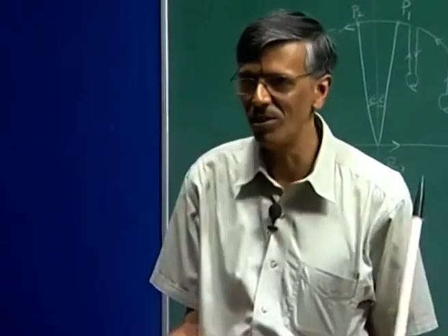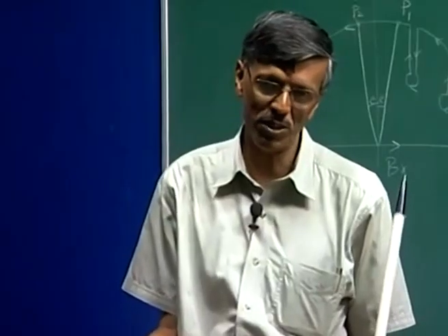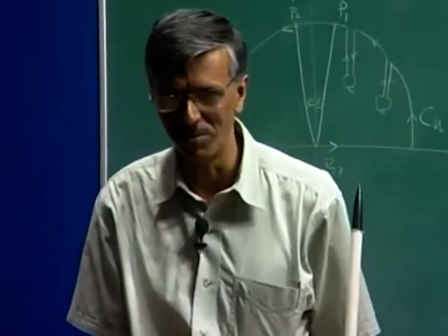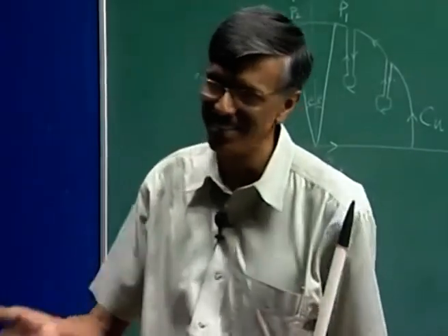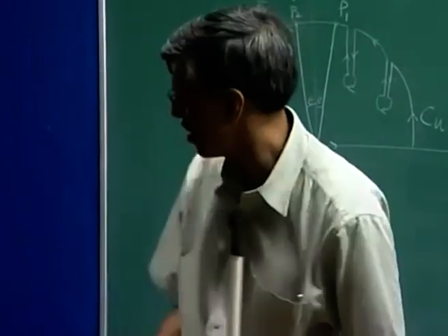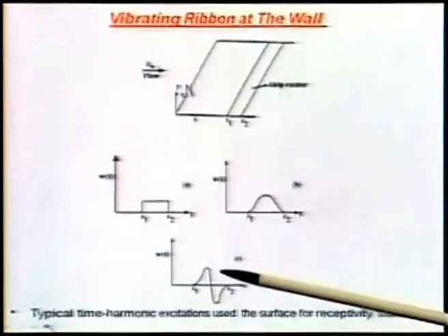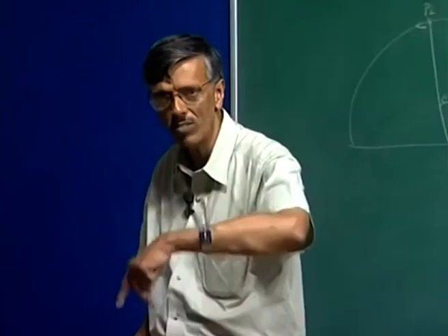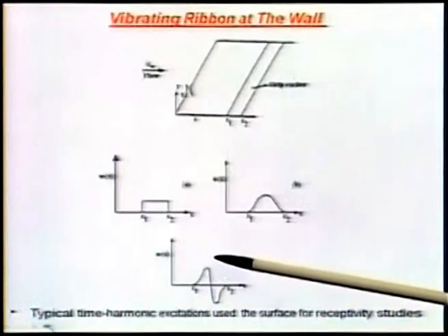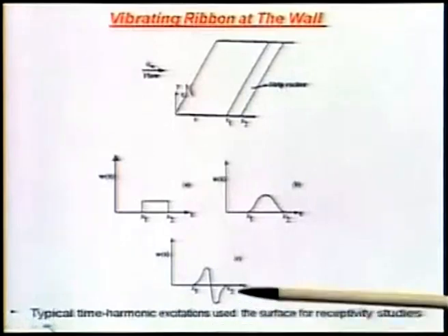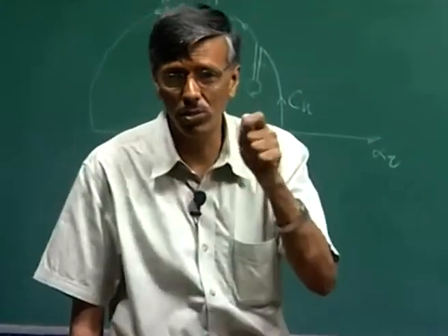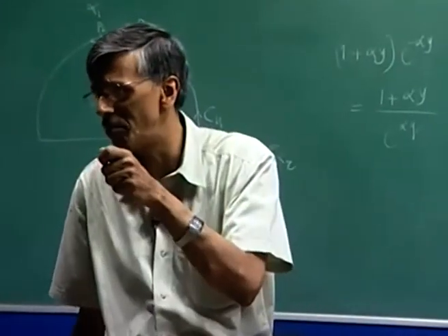See, this is something also you must ensure, that when you are computing, you should not violate any of the conservation principles. And this particular excitation satisfies the conservation of mass at each time, because this is the scenario at any time. What will happen? This whole thing is harmonically fluctuating at a frequency omega naught. So half the cycle this will remain positive, other half it will be negative, and this also will correspondingly flip. But at each and every instant you are going to ensure there is no net mass added.